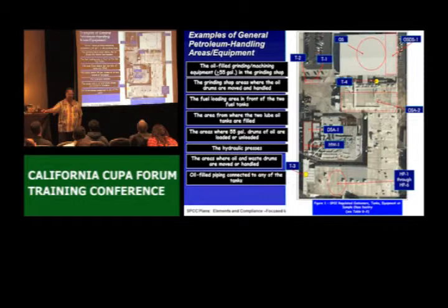Particularly for a number of containers in there, it's up to the engineer to determine whether that's adequate. The bigger problem really is not that they picked 110% versus 24 hours of a 25-year storm. The bigger problem is the facility left 5 inches of rainwater accumulating in there and didn't pump it out. Now they have insufficient containment. That's the bigger problem.